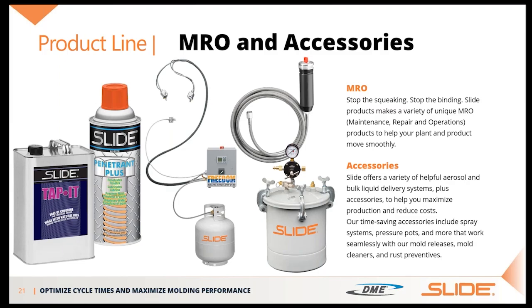It'll penetrate, so if you've got something that's rusted up, it'll bust it loose. It's a good cleaner. It'll lubricate. I've got customers that use it running a bandsaw blade. I've seen that done instead of using tap oil or cutting oil, which we have. They'll use the Penetrant Plus.